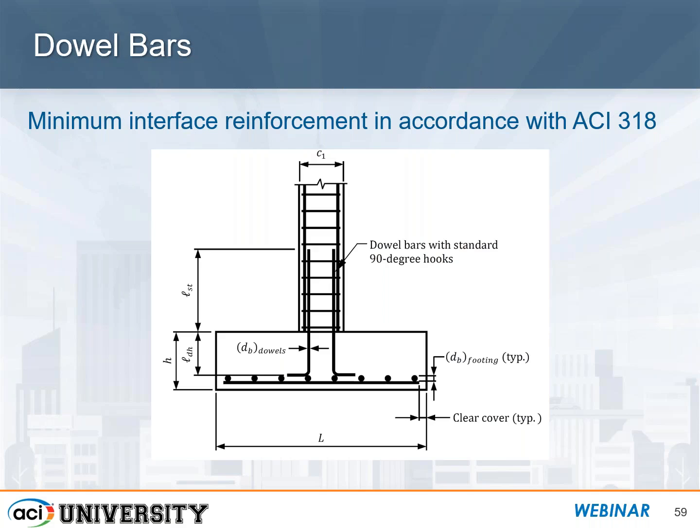Now, that's just the basis of ACI 117. If you had, for example, a beam that was supporting something very sensitive to deflection, then as I was designing this beam, I might consider taking into account a decrease in overall beam thickness and calculating my deflections that way.